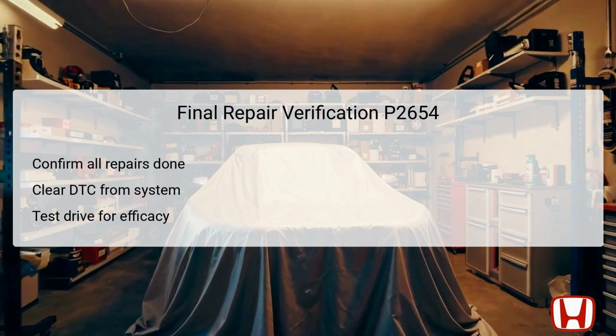Once all the necessary repairs have been completed concerning DTC P2654, it is crucial to confirm that all procedures were accurately executed. Begin by clearing the DTC from the PCM using diagnostic tools such as the HDS. Following this step, conduct a test drive to evaluate the vehicle's performance and verify that the issue has been resolved.